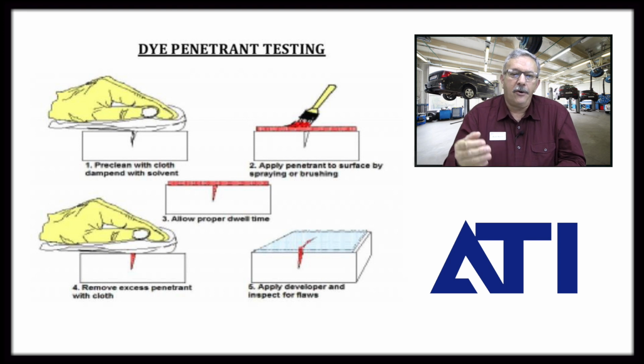That tells you that that part has some issues, and I wouldn't want to use the part. So again, it's something that you may not do that test yourself, but I would make sure the people that you're buying the part from have done that test, and they can tell you that that's a quality part and that it's had a dye penetrant test done to it, just to make sure that it's in fact good, and you're not going to end up with some problems from it later on. Those cracks under pressure can open up and create some issues with drivability.